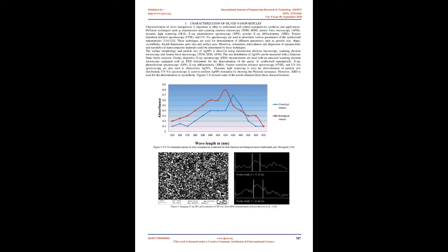Sputtering method. Direct current, DC, magnetron sputtering has long been used to fabricate thin films, nanostructured coatings, and nanoparticles of various materials, including metallic oxide, nitride, and carbide films, to produce silver nanoparticles. By this process, a silver target was bombarded by inert gas ions and silver particles emerged. Chandra et al. 54 have used a high-pressure sputtering method to fabricate silver nanoparticles, 3 to 60 nanometers.